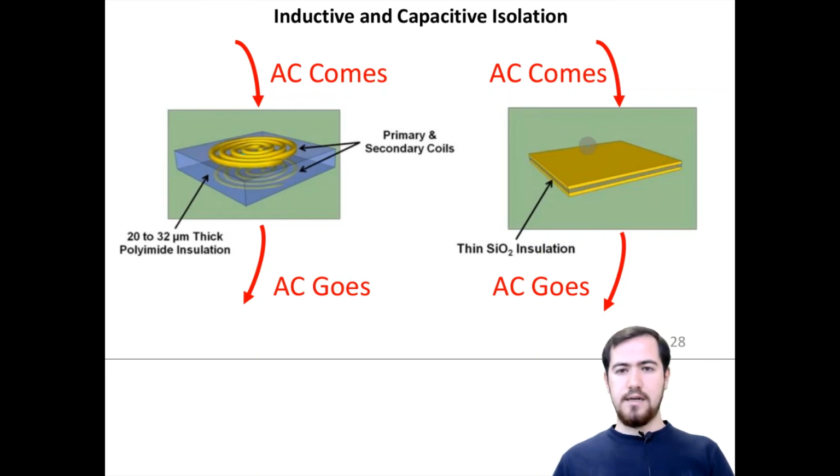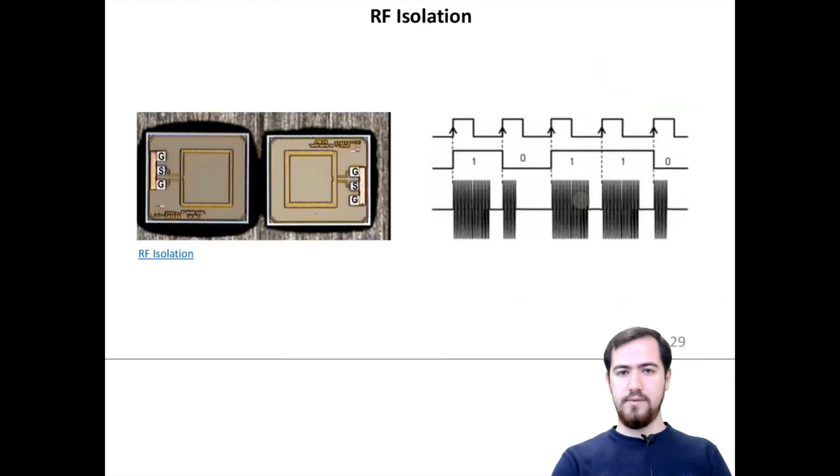And as we discussed for the gate driver, the gate structure of the MOSFET, the capacitive couplings are also able to carry the current for an AC signal. Here the isolation barrier is shown, which is the silicon oxide between these two conductive layers, and we can carry the AC signal through that capacitive isolation as well.